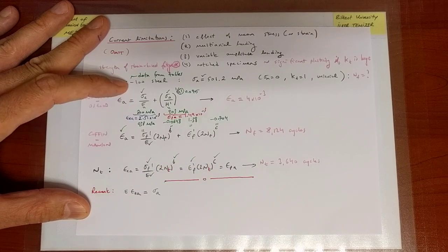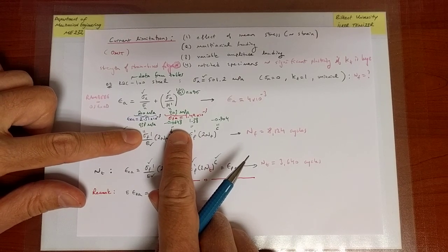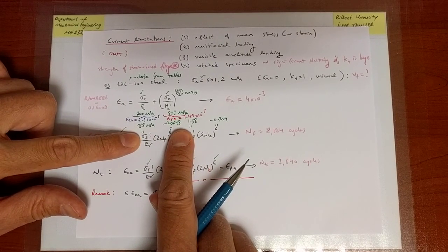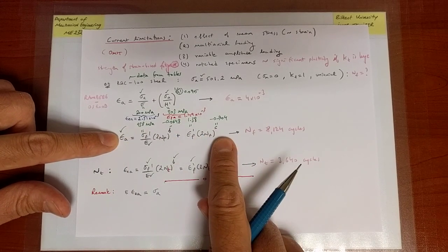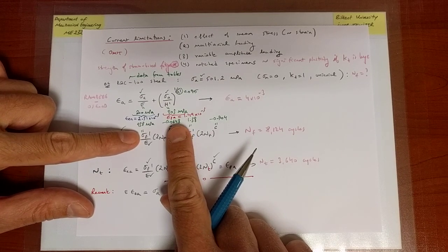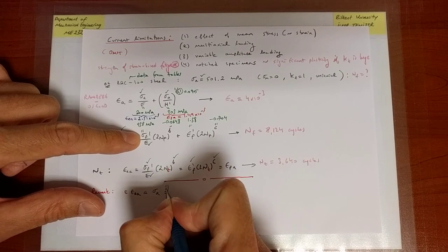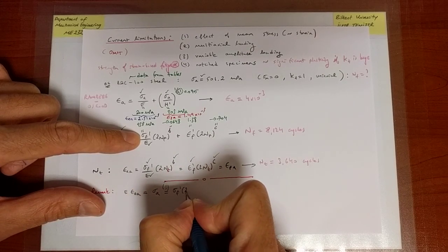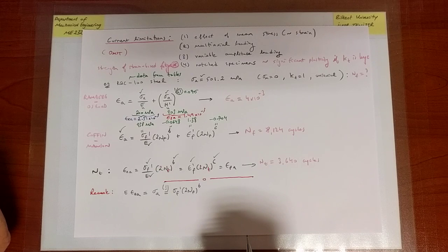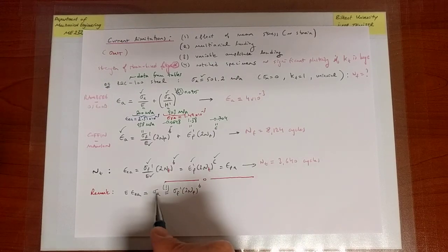stress amplitude. Now, at the same time, we also said that the total elastic strain is associated with the elastic contribution to life, or the elastic strain-life relation. This portion of the total strain-life relation is associated implicitly with the elastic portion of the strain amplitude. So when I multiply this likewise with E, we get, and let me put an exclamation mark there, sigma f prime (2Nf) to the power b, right? If on a log-log scale epsilon EA versus Nf is linear, then stress amplitude, which is E times epsilon a, is also on a log-log scale linear with respect to Nf.